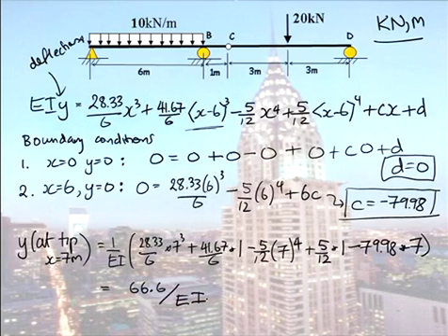So just to go over that again, quite often you're given EI in units of Newton millimetres squared. How do I know they're the units of EI? Well, E is in megapascal, Newton per millimetre squared usually, and I, if you've done your class today, you know we'll have units of millimetres to the power of 4. So that gives you newtons millimetres squared.